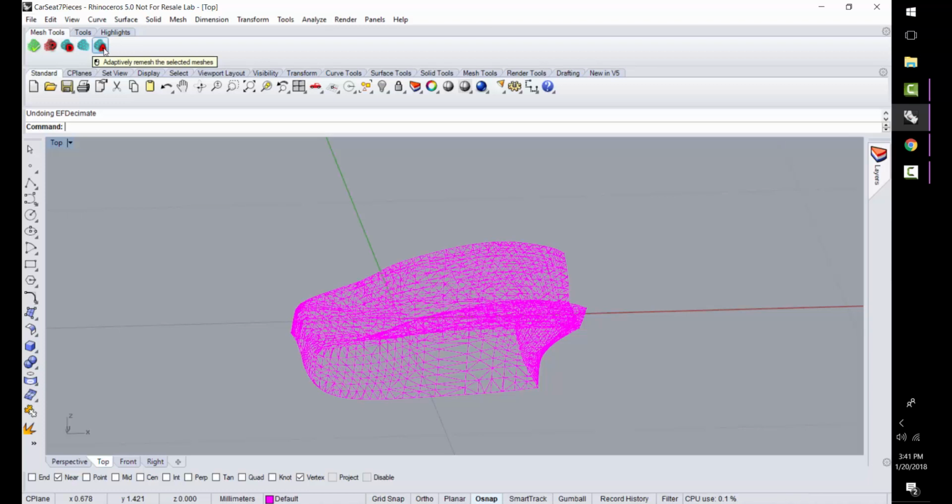The adaptive remesher is different in that you're allowing the computer to make the best choices for you. The algorithms are going to create a mesh that they see would be the best mesh available. It looks at the planar surfaces and creates a sparser triangle count along them, but it keeps the fidelity on curves, so it throws more triangles around curves to keep the curve fidelity.